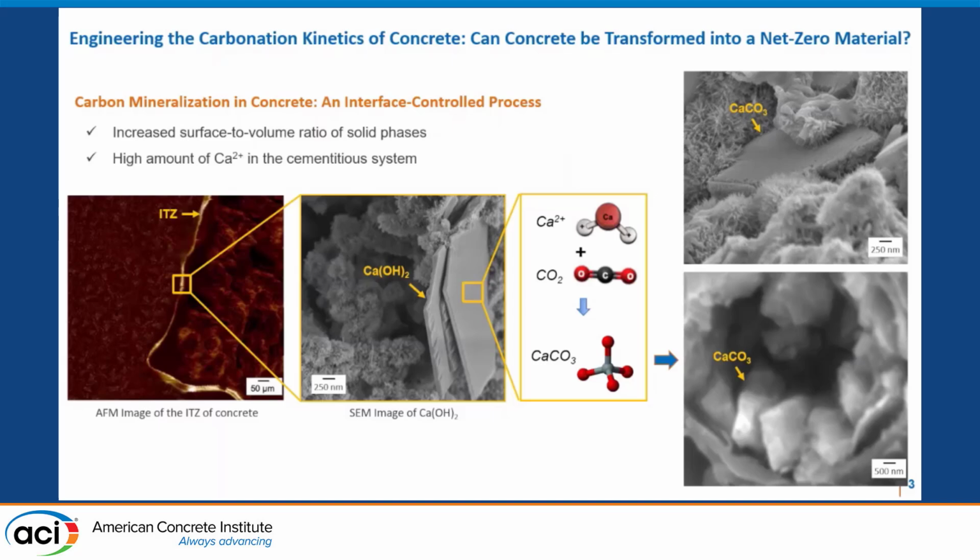Keep in mind that when we are increasing the amounts of supplementary cementitious materials, we are essentially running a second reaction, which is the pozzolanic reaction, which takes up all the calcium from the cementitious matrix.